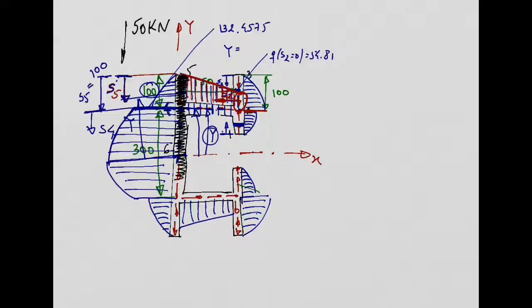Okay? So this is our cross section. Right? And then you can see how the shear flow is distributing on the walls of the cross section. Okay? Anyway, you see more or less how this works? So what I propose to do now is, so this is what we call an open cross-section. When you have free edges in a cross-section, we call this open cross-section. And what we did so far is all you need to completely characterize the shear flow in the cross-section.